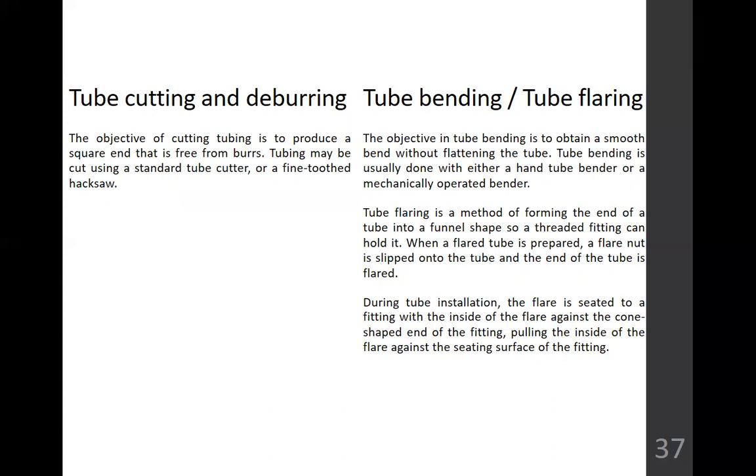So, check na siya, libro na. During the tube installation, the flare is seated to a fitting with the inside of the flare against the cone-shaped end of the fitting, pulling the inside of the flare against the seating surface of the fitting. So, check nyo doon ha. So, reference nyo. May mga procedure to ng cutting na drawing doon.